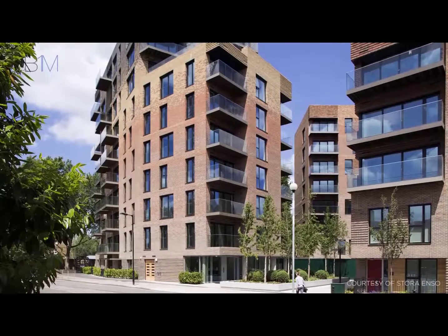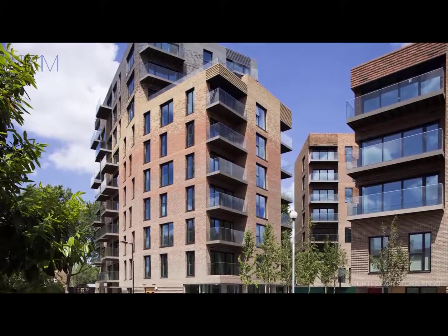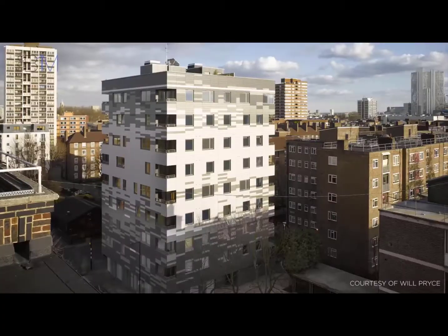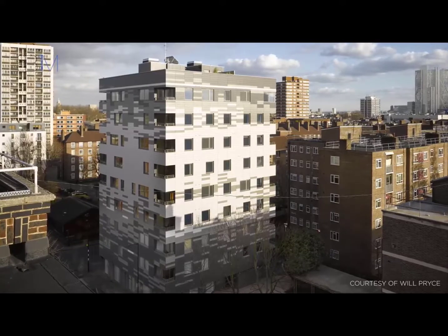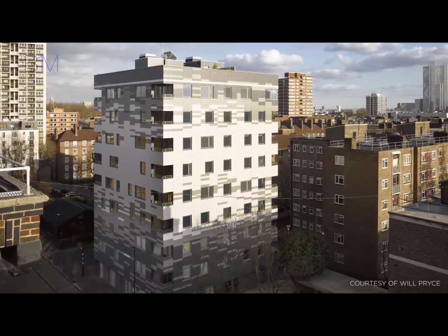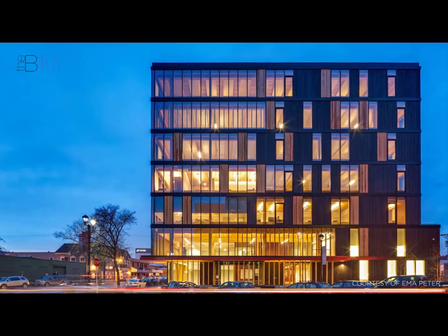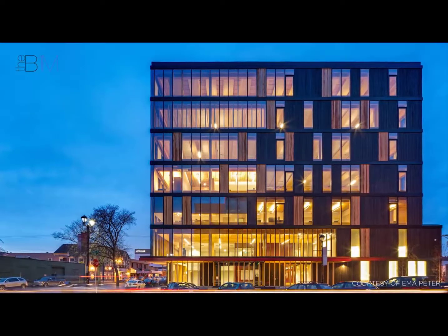CLT uptake and use was initially driven by the material's sustainable credentials. However, in recent times, the resurgent construction market that is placing pressure on traditional materials, along with increased awareness, has bolstered adoption. While early CLT buildings were predominantly small, low-rise structures, the material is increasingly being considered for taller schemes. Since architect Walt Thistleton built the first timber skyscraper, or ply scraper, in 2009, tall timber buildings have been planned around the world. In the past 5 years, towers of 30 metres, constructed from CLT, have risen in Australia, America and Europe.